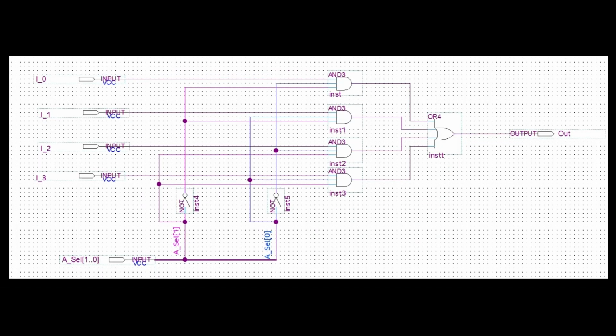Before making the large size multiplexer, we must understand how a multiplexer works first. So right here, we have a 4x1 multiplexer, where it accepts 4 inputs and produces 1 output. And we have the selector right here with S1 and S0, and each of them are connected to AND gates. The most concise explanation is that it depends on the selector.